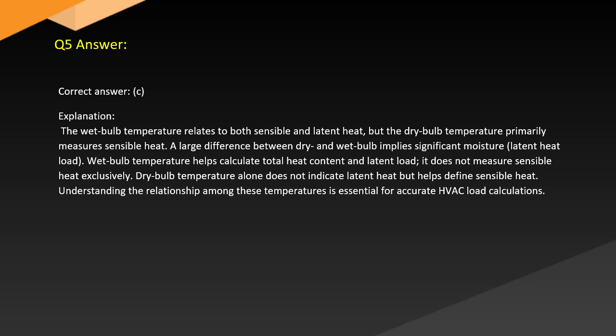It does not measure sensible heat exclusively. Dry bulb temperature alone does not indicate latent heat, but helps to measure sensible heat. Understanding the relationship among these temperatures is essential for accurate HVAC load calculations.